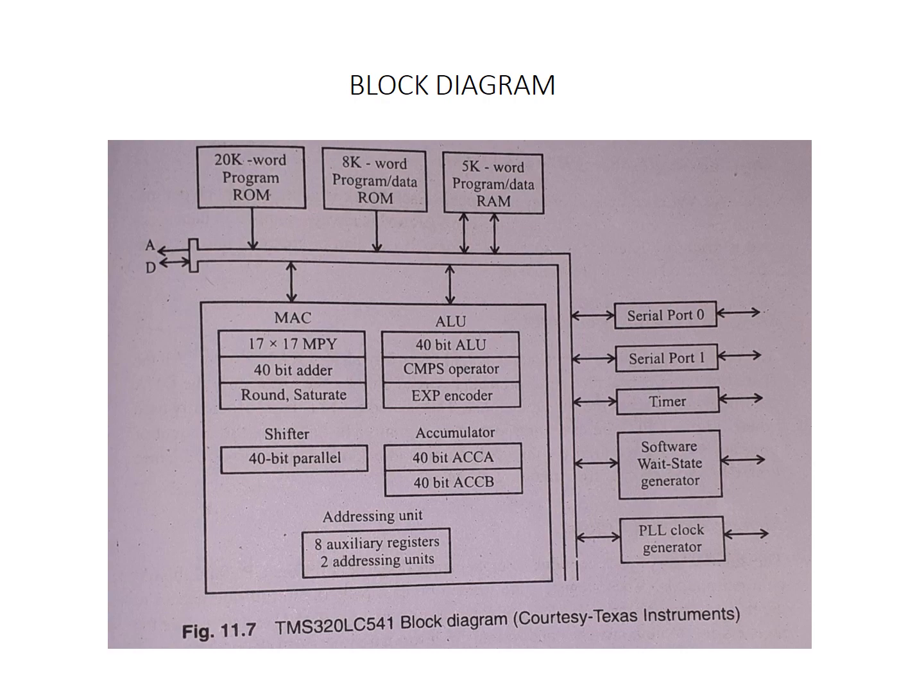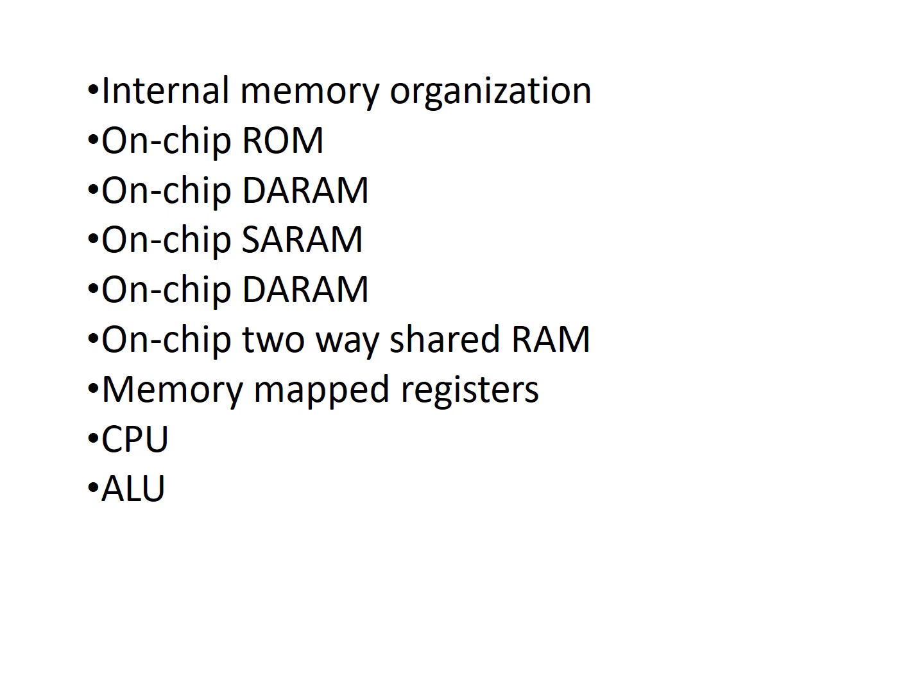This is the block diagram of the TMS320LC541. Here the internal memory organization: on-chip ROM will be present, on-chip DARAM will be present, on-chip SARAM will be present, on-chip 2-way shared RAM also, memory mapped registers, CPU and ALU will be present in your diagram.